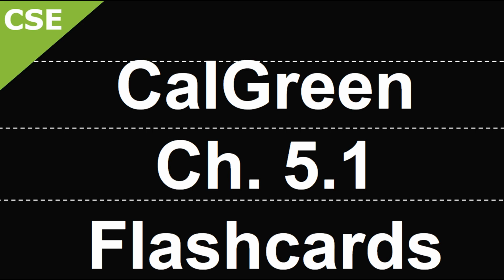Level 1 chargers, it's common to get around 4 miles of range per hour of charging. With level 2, it's common to get around 20 to 30 miles of range per hour of charging. So a level 2 is a higher power, which means faster charging, but it's also more expensive as a system. Remember that level 2 charging stations use AC, or alternating current. Electric vehicles have chargers built inside the vehicle to convert AC power to direct current DC power for the battery.